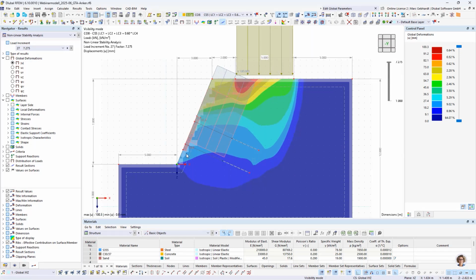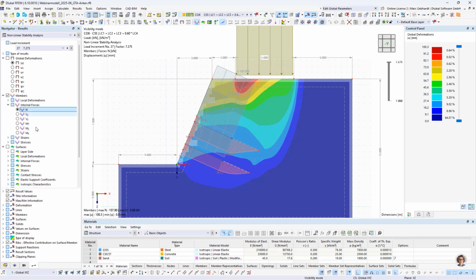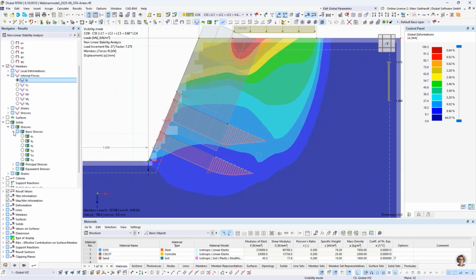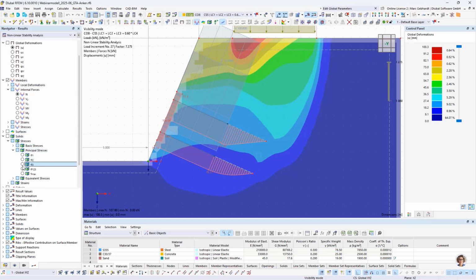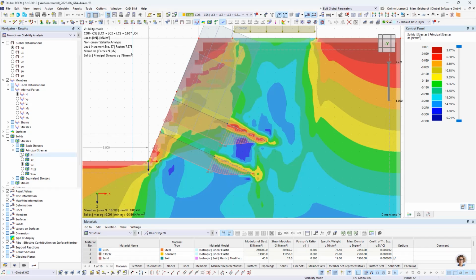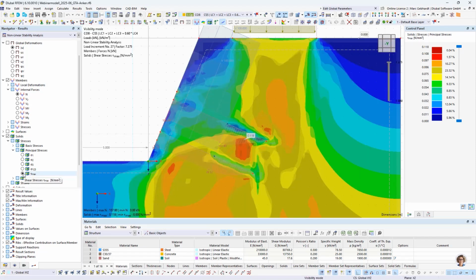So you can check in the middle of our volume, and we want to see the internal forces, the normal forces in the anchors. You see here the pile part is raising up and going to a constant value for the tandem part. And furthermore, we want to check the solid stresses, basic compression stress, see here, and the anchors have a high influence as we see. Better we see it also on shear stress, maximum shear stress. You see it, yeah, wonderful.